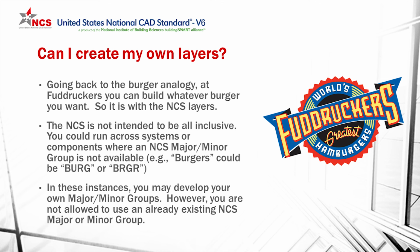And so you can develop your own major and minor groups. However, the rule is you're not allowed to use an already existing National CAD Standard major or minor group. So if you are going to create a new major or minor group, you need to go and check the list of the major groups and minor groups in the National CAD Standard and make sure it hasn't been used. And again, like I said before, they're alphabetical, so it's easy to check.